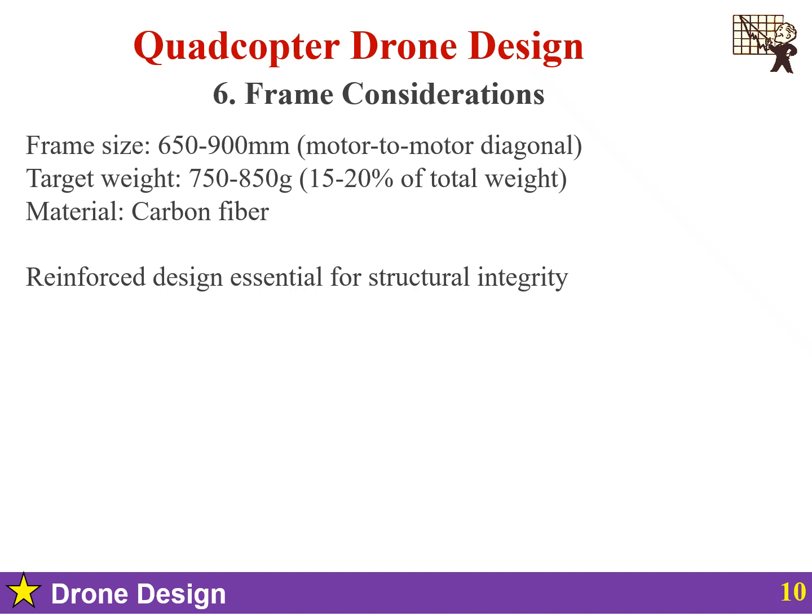So, what are the structural engineering requirements for this? Load analysis. The frame must withstand multiple simultaneous loads. Static loads: 5 kg weight plus 2 kg payload. Dynamic loads: 2 g of maneuvering forces. Thrust loads: 2550 grams per motor mount. Landing impact potentially of 400 to 500 grams or 343 newtons. The vibrational energy of 100 to 150 Hz frequency from motors and propellers.